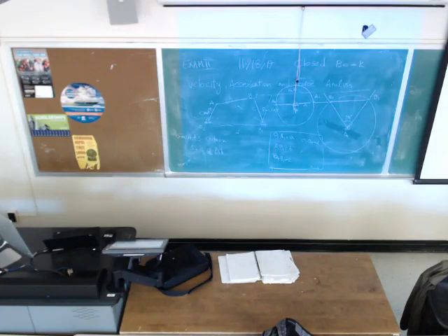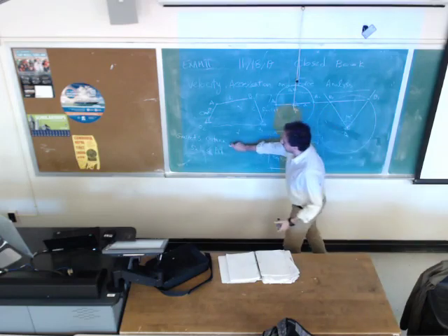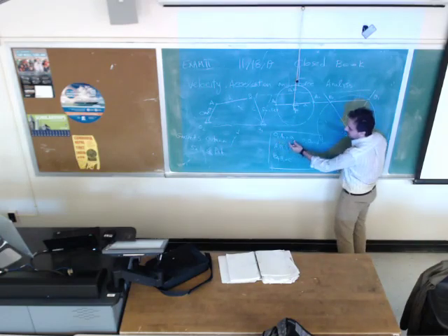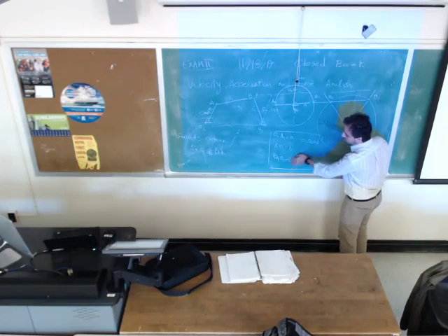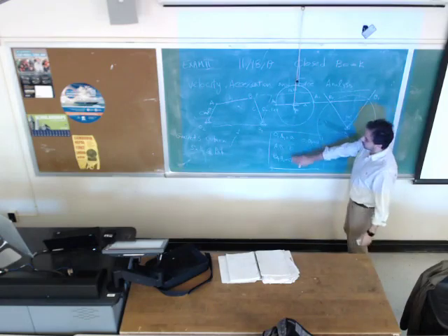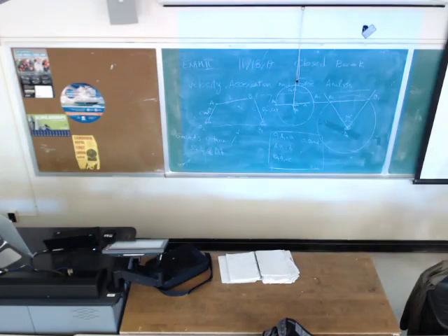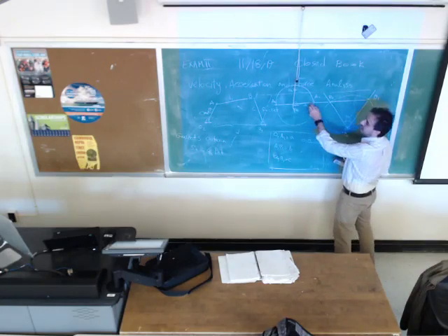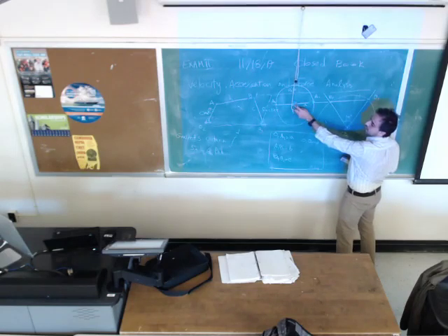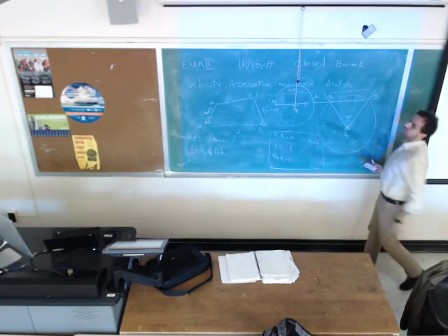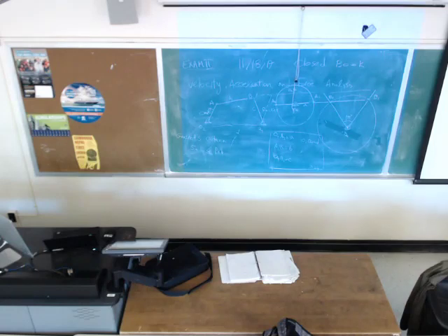If it doesn't satisfy the criteria, if O2A1 is not the shortest, or the summation of the shortest plus the longest is not less than the summation of the other two links, what you need to do is change the location of O2. Here you picked this point, then you have to change O2, get the new values, and check the criteria.